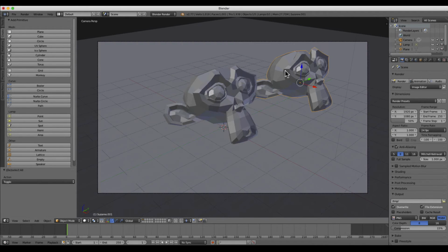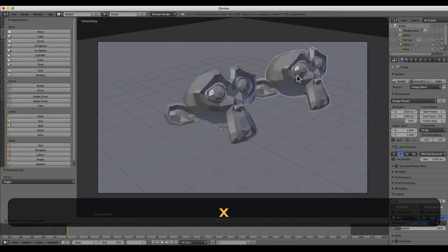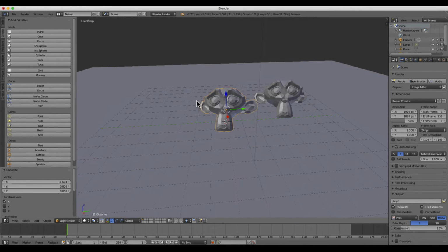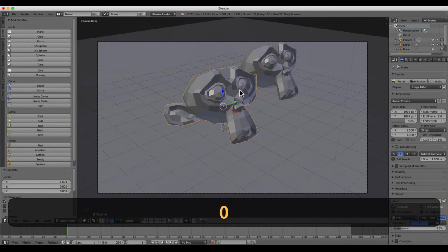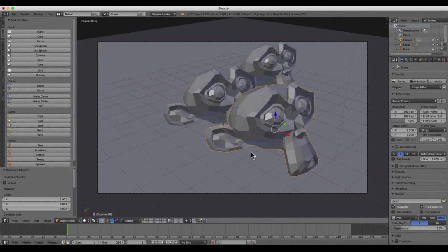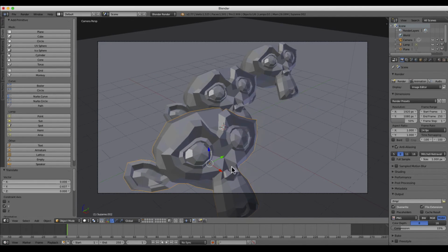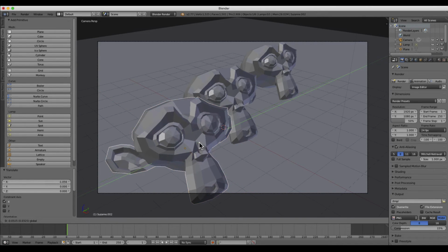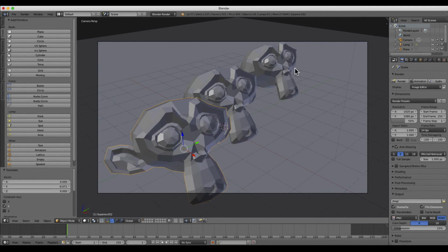Now we can look through the eyes of our camera and see what this is going to look like. Let's move this over a little bit more so it's a little bit more interesting, something like that. From the camera viewport, as long as I don't move, I can still manipulate these objects. If I hit Shift D again to duplicate this monkey head, I can constrain it to the X axis by hitting X and dragging. Left click to accept that, and now I want to move this over so that it's a little bit in front. So I have 3 monkeys kind of in a row here, a little bit like that. Now they're all on the ground, but they're all kind of in a row.